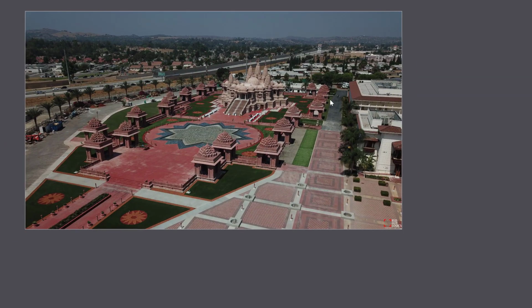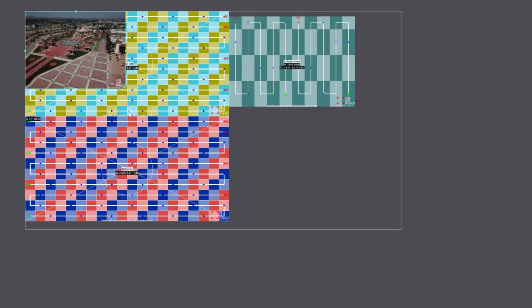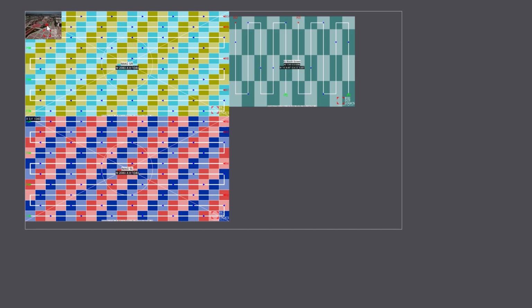It's gonna cover up your entire whatever you have done. You could hold down Control key on your keyboard, and this will give you the option to resize this into a smaller size. So if this was your logo that you're trying to put on a screen, you can also hold down Control key to move it around where you want it.